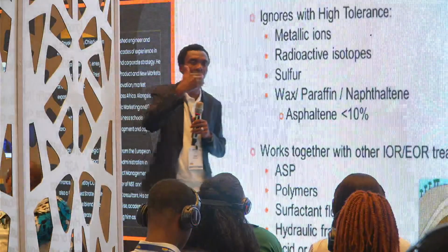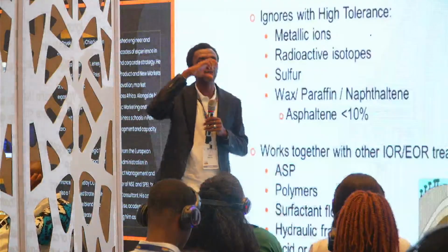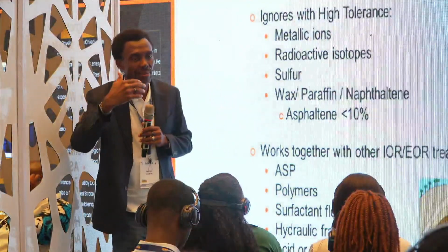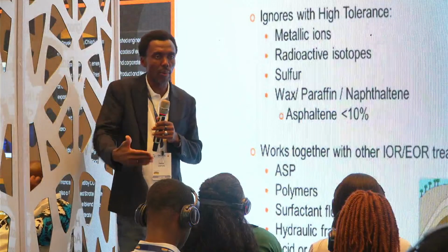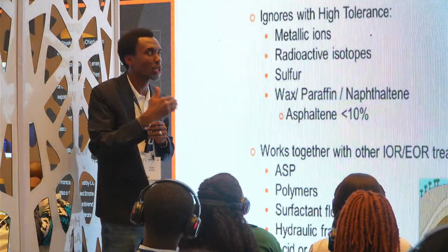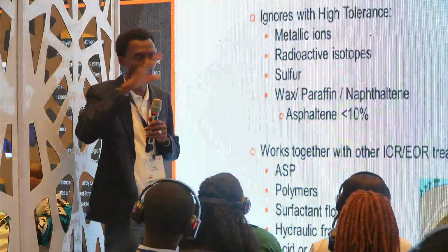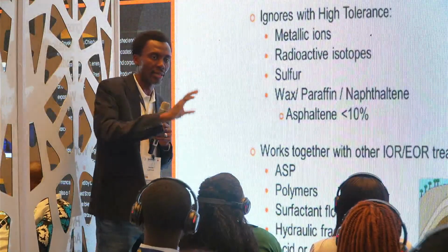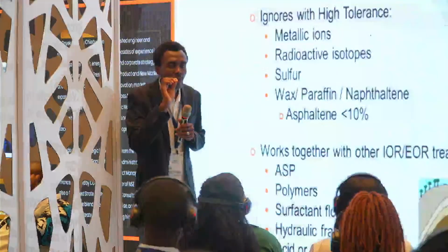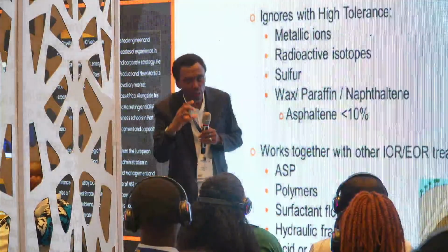And in petroleum engineering, to define what skin is: something that causes an impairment immediately close to the wellbore, not allowing oil to flow the way it should into the well. I can give a technical definition, but I'm just trying to define it in layman's terms. So what you do is to apply acid and see if you can just peel it off.